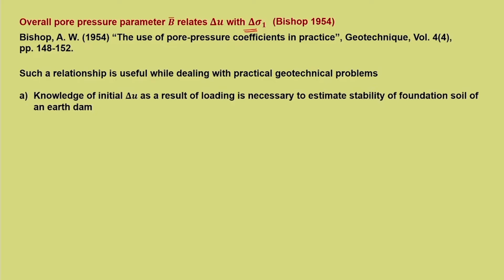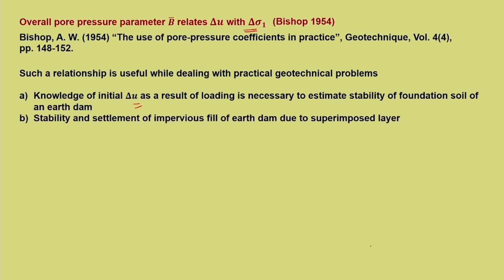Knowledge of initial delta U as a result of loading is necessary to estimate the stability of foundation soil of an earth dam. Maybe for a drained condition after a pretty long time, what will be the state of the soil? For that, we need to know what kind of pore water pressure gets developed due to loading, which is very essential for situations like the foundation soil of an earth dam. Other cases are stability and settlement of impervious fill of an earth dam due to superimposed layers in staged construction, and increase in stress due to rapid drawdown.